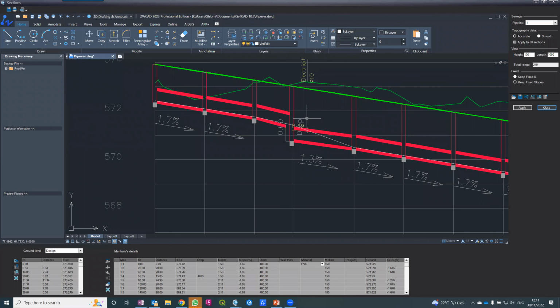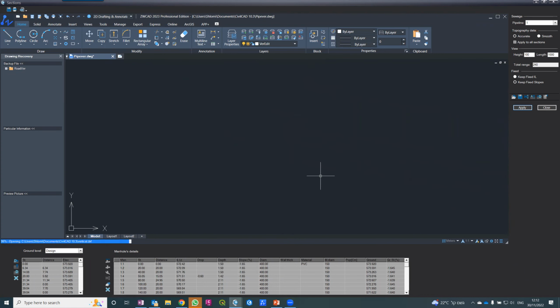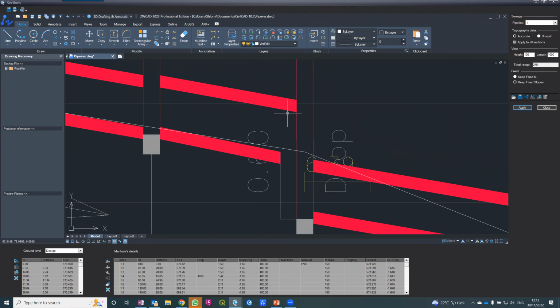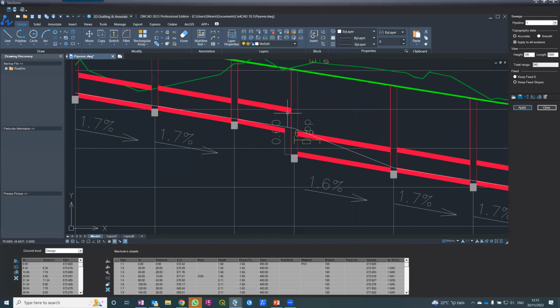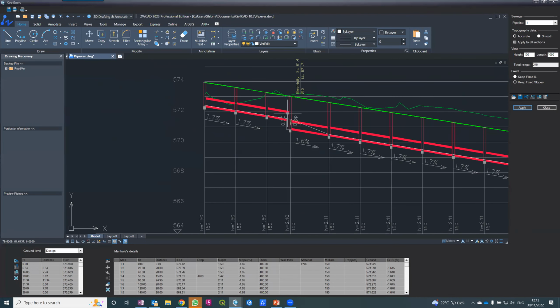The only thing is that I didn't define for the software what to do in terms of slope here. So it just used the same invert level. So the slope changed, you see it's a little bit going down like this, 1.3. So I can fix it easily. This is very simple. Just let the software fix it to be 1.65 again. And that's it. Now I've even corrected the slope. Before I close this session, a few other things.